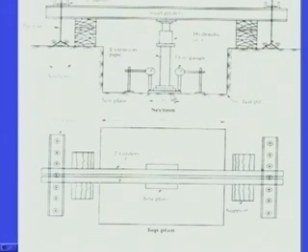Test plate is placed and over that a column is there, and from this column, which is the extension pipe, the load is applied by hydraulic jack and the reaction is taken from these steel girders. Now, these steel girders may be fixed by anchors. So, the reaction is taken by the soil or the anchoring action.